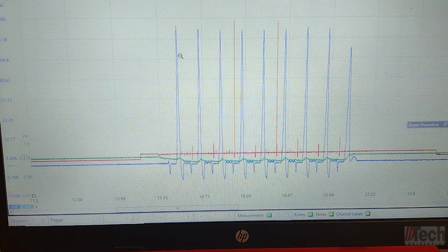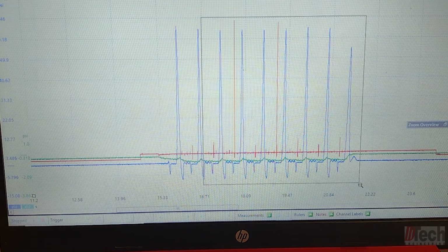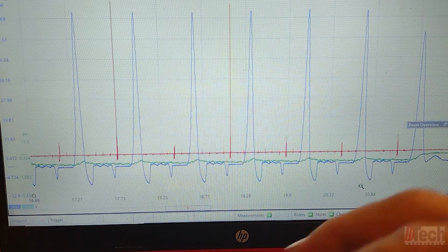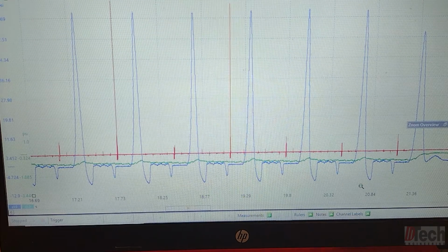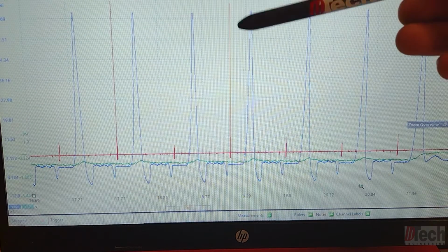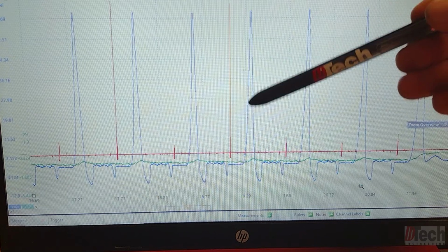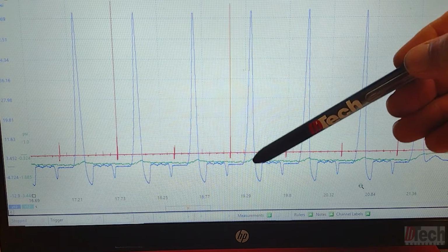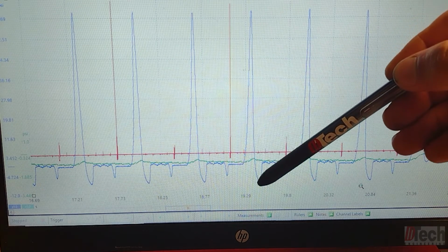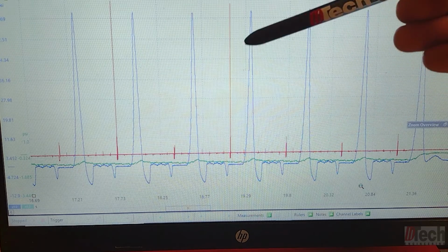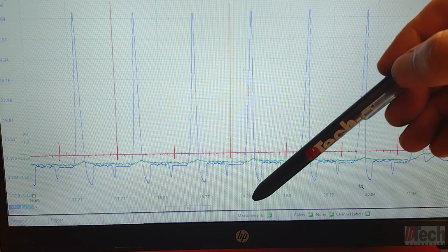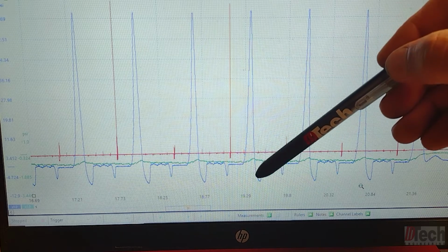Now right away you can see down at the bottom there's a big difference from cylinder 1. Because we know we are leaking, our tower does lean, has a shorter side here on the right side, and then it goes into deeper vacuum because we've lost volume. That is why that is so deep.